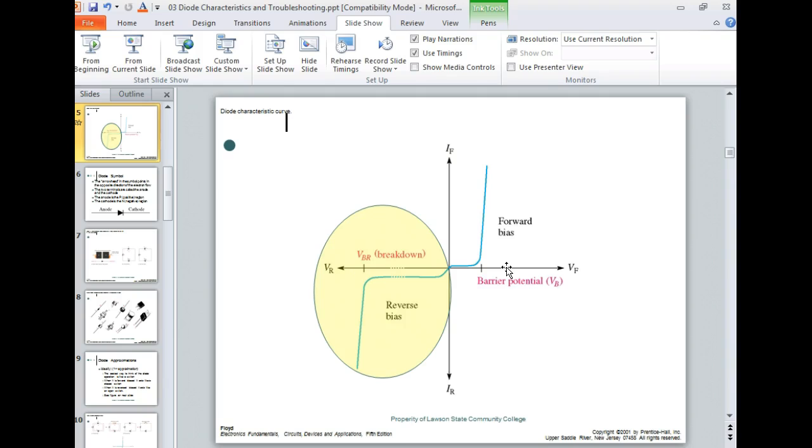We'll calculate the current. Then when we get it broke over, we'll come up and take a soldering iron and put it up next to it. We should expect the current to go up. We'll get some freeze spray and spray on it, and the current's probably going to go to almost 0. So we'll see that the reverse current is controlled by temperature. So the forward current is controlled by it being forward bias. We don't get it hot enough to shake loose a lot of minority carriers in the forward bias situation. But that reverse bias, that's when we can really cause problems with temperature.